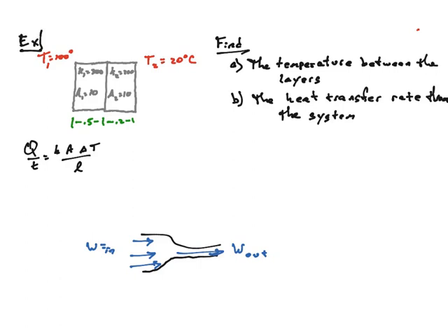Because this side of the pipe is really, really big, you have a heck of a lot of water going through this opening. And since this side of the pipe is really small, if you need that same amount of water to come in per second, or to go out per second, it must be moving a lot faster to keep up with the intake. And so in fluids, this is called the mass flow rate, or the volume flow rate. The amount of water coming in per second must be the same as going out per second.